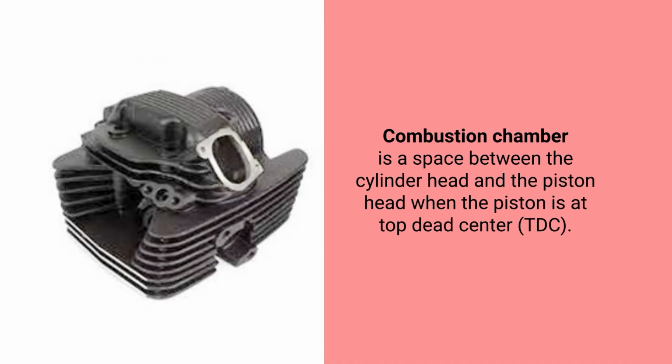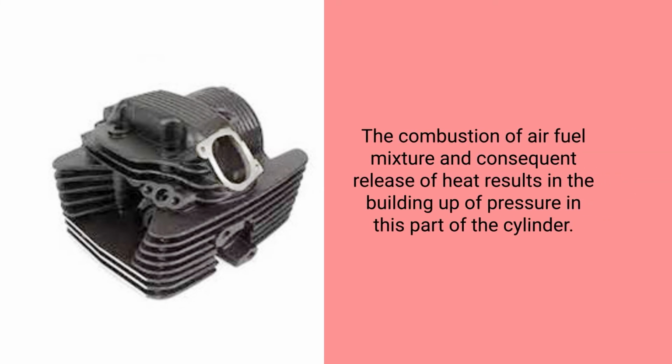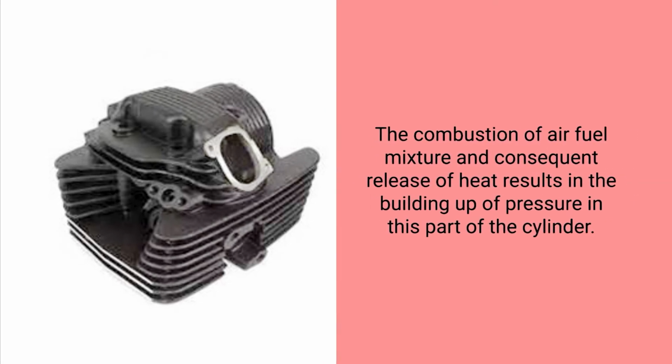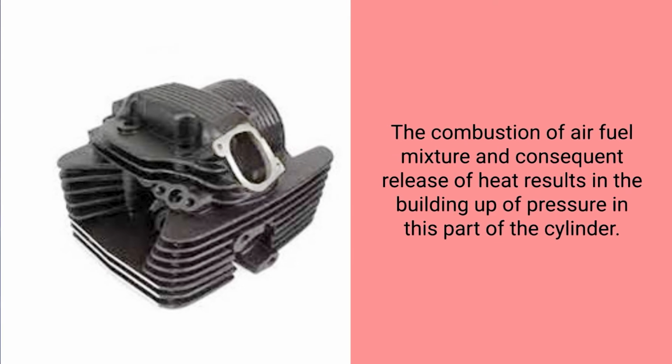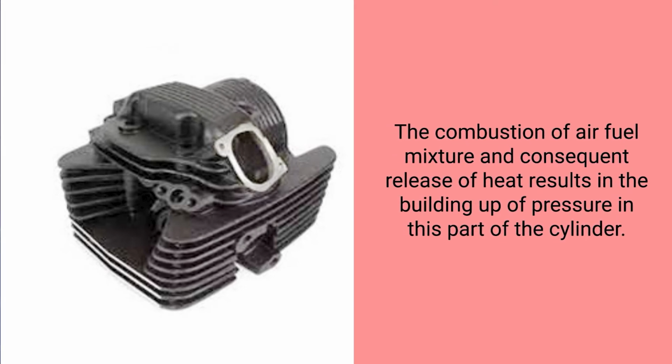Now, second is your combustion chamber. The combustion chamber is the space between the cylinder head and the piston head when the piston is at the top dead center. The combustion of the air-fuel mixture and the consequent release of heat result in building up of pressure in this part of the cylinder, and this pressure generates the movement of the piston, and it further moves the crankshaft and the connecting rod.